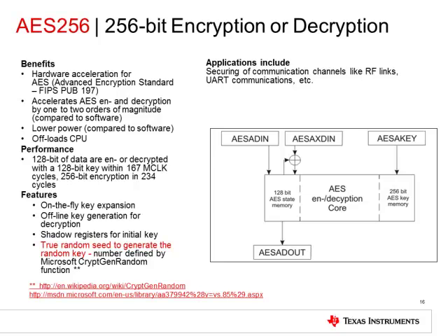The FR5969 device also provides a random number stored as a seed for a deterministic random number generator. This unique seed is programmed at test and is generated by an offline test programmer using a cryptographic random number generator. This is useful for creating unique serial IDs and also for key generation.